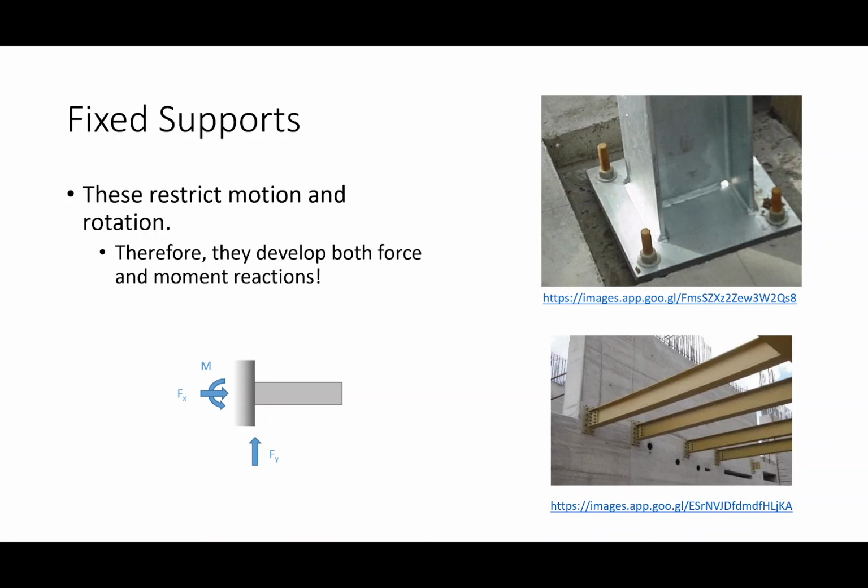So today is a simple support. And by simply supported, if I use the term simply supported, I'm meaning hinge roller or pin roller. Simple supports don't have moments. Fixed supports do. So if you want to know a terminology definition there, that's what I mean, okay? Everybody with me so far?